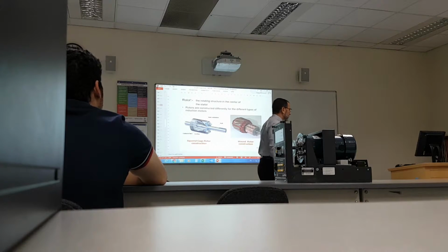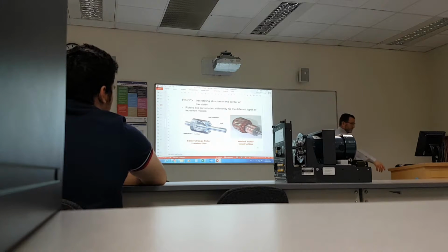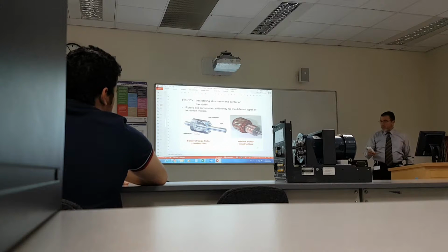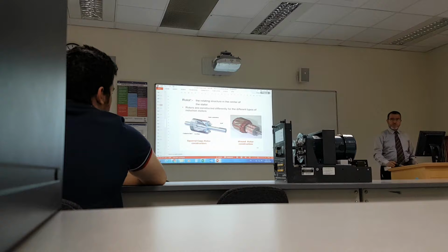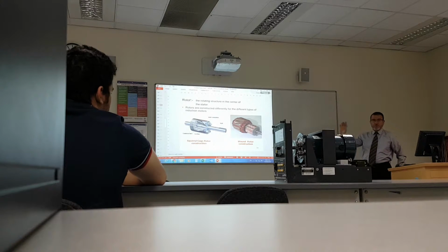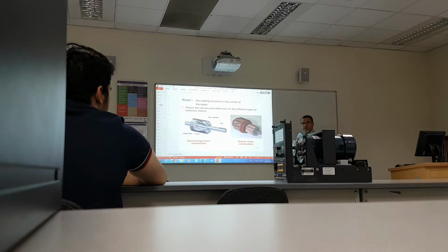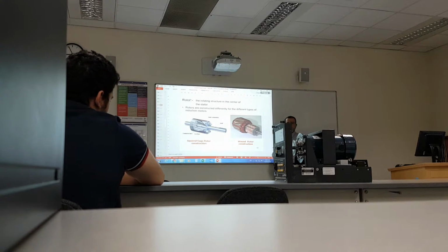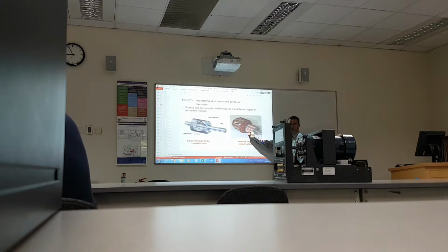What should I know about the wound rotor motor? Why do we use it, first of all? What's the main purpose? Squirrel cage motors are beautiful. They are low maintenance, reliable, and low cost. But high initial torque, right? No, squirrel cage motors have lower initial torque. We're talking about the wound rotor. It has certain features that you pay for, such as reduced starting current, and also higher starting torque.